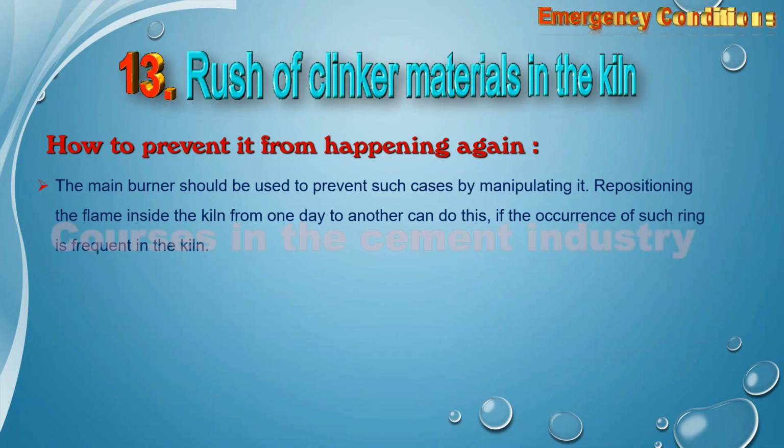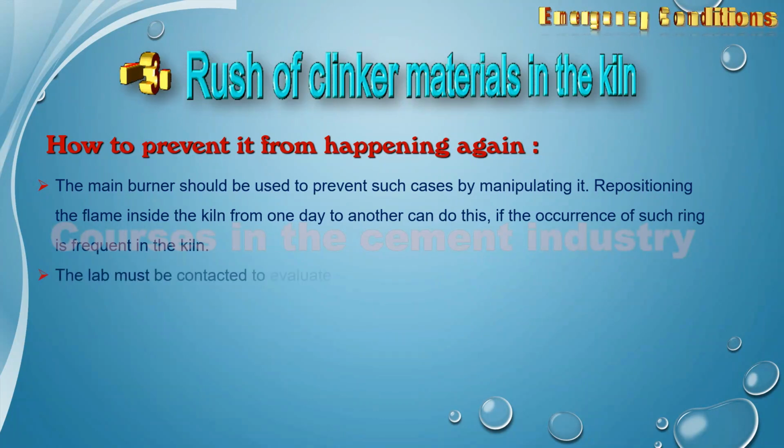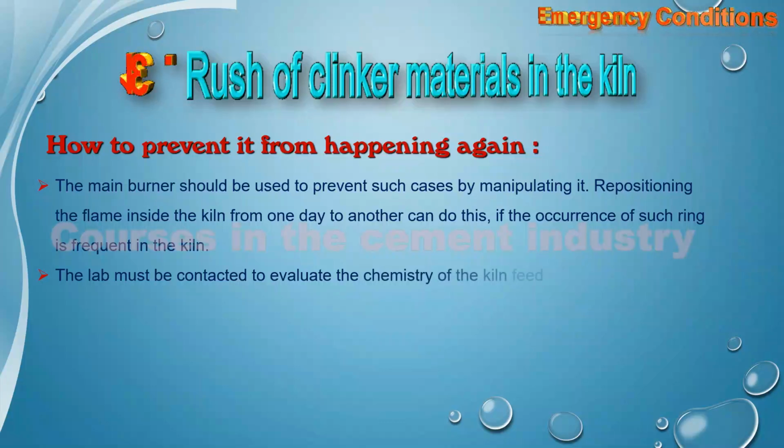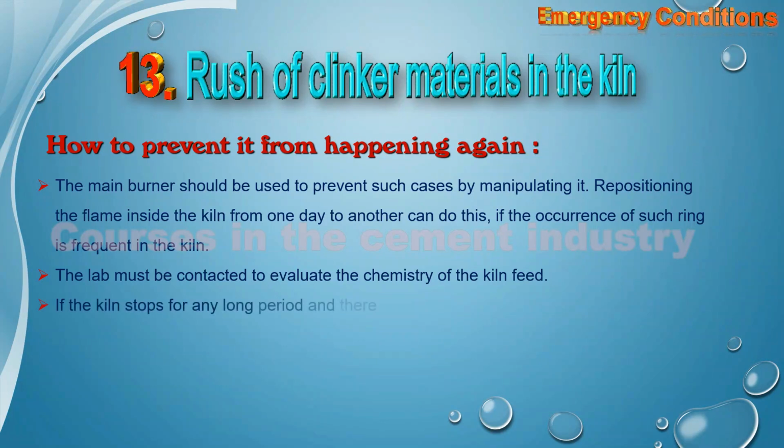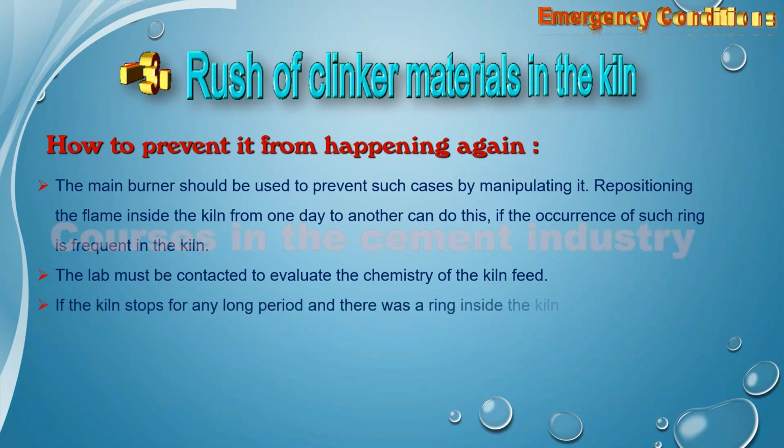2. The lab must be contacted to evaluate the chemistry of the kiln feed. 3. If the kiln stops for any long period, and there was a ring inside the kiln, destroy it.